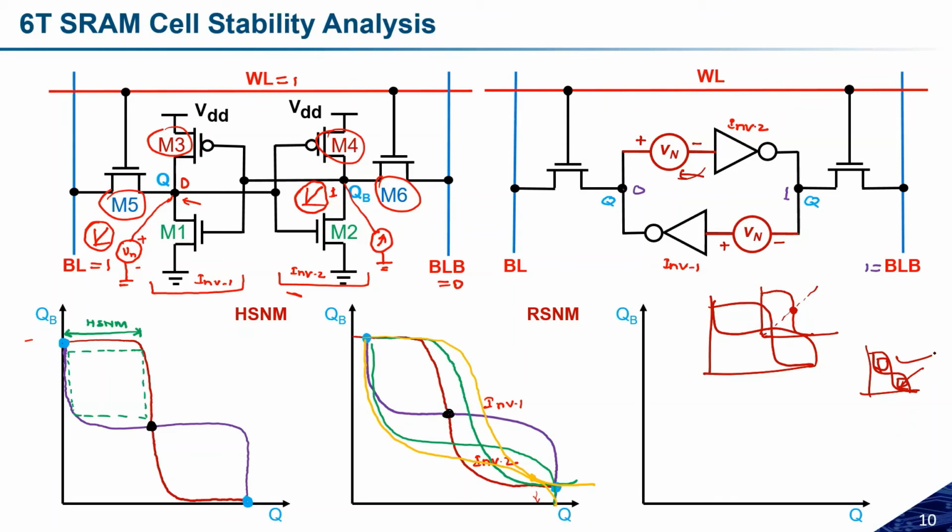Yes, it is absolutely correct that while simulating and calculating, we need to apply the real voltage to change the logic. But in reality, to make it stable, we must consider additional noises, which can be anything and can alter the logic. So we don't know what kind of noise it is. But we are simply assuming that the noise which we are getting is simply increasing the voltages at the input of both the inverters. So this is what we can understand, or we can assume. Okay, you got the answer?